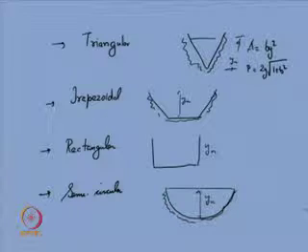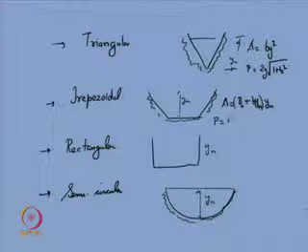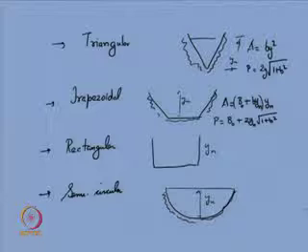Right. In the trapezoidal section you have seen area A, if the bottom width of the trapezoidal channel is equal to b 0, so we are following the same convention, so b 0 plus, and the side slope if it is 1:b, b y n, your wetted perimeter P is equal to b 0 plus 2 y n root of 1 plus b square.